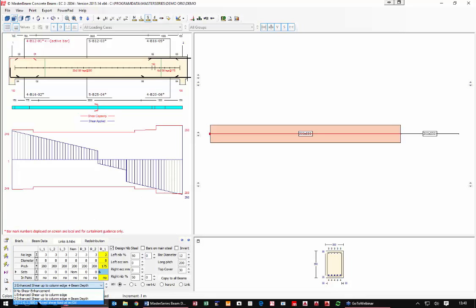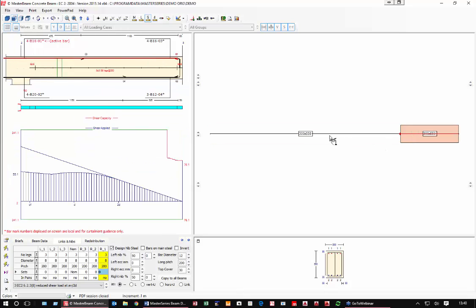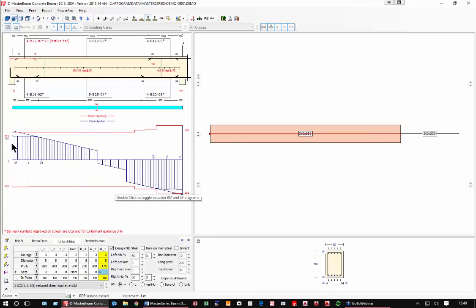We also have in the Eurocode this great reduction in shear that we can apply, which is like a dragged shear reduction, and it can get quite hairy because it's doing a curved reduction in shear. And can I use that with no additional reinforcement? Again, in this case it would still require those additional bars, and type that in. So that's the concrete design.